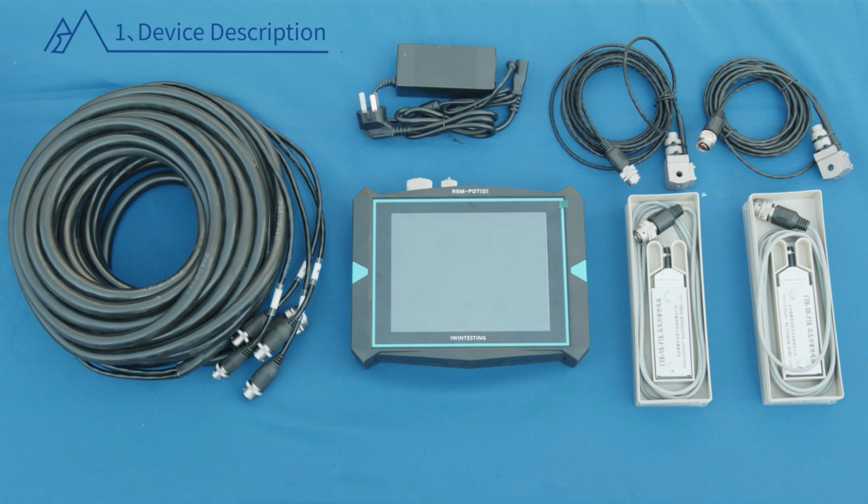4. It is recommended to use a special high-strain hammering system that integrates the heavy hammer, the guide frame, and the hook, and can fix the free-falling track of the heavy hammer. It can ensure site safety and reduce hammer eccentricity. 5. Set up a safe area and establish a working surface.